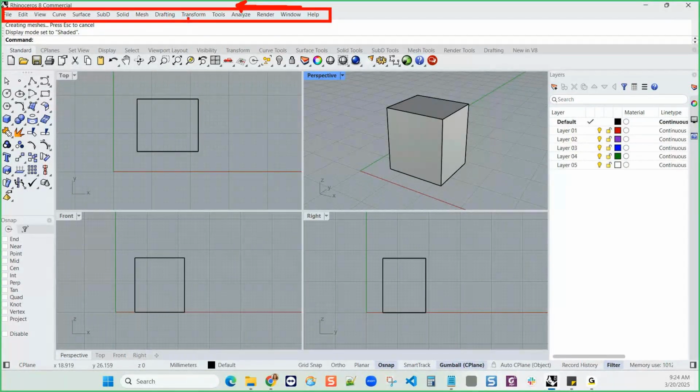When you have geometry, you can transform it. So you can move, copy, scale, rotate, trim. Trim and extend, or actually trim, split, and extend. Trim and split are on the edit menu. Extend depends on whether you have a curve or a surface, so you'll find those on their respective menus. And there is a way to find out from Rhino where commands are located, and I'm going to show you that here in just a moment.